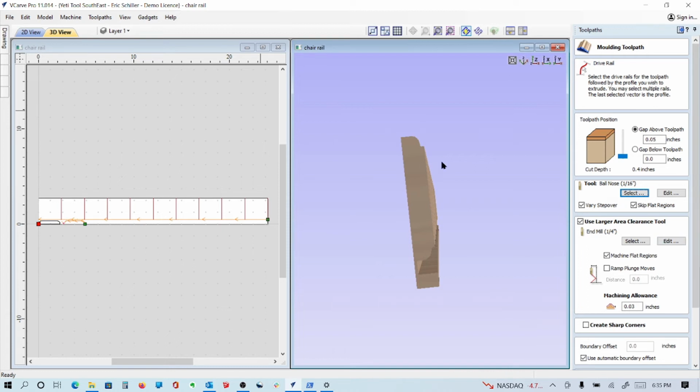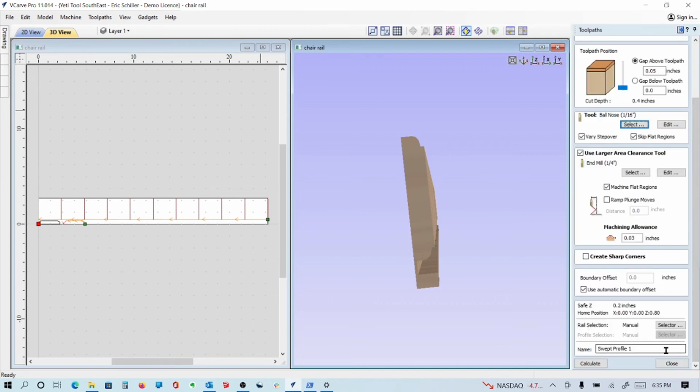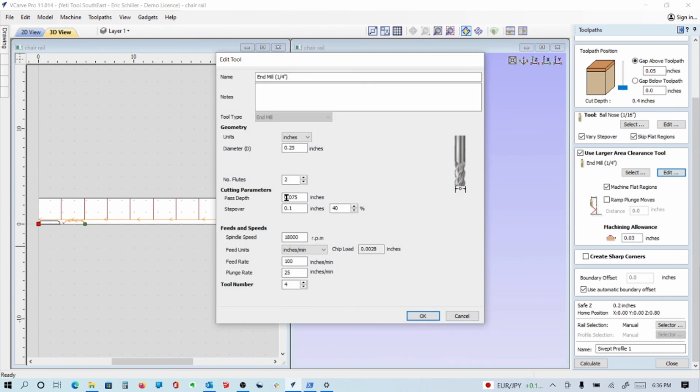And this is a flat one, so obviously if we used a bigger tool first, a 1/2 inch or 3/4 inch cutter, surface that, and then come back in with a 1/4 inch cutter to hog this out, and then the final cutter, the 1/16 inch tapered ball nose I'm looking at, to come in and clean that. But I'm just going to leave it like this for this time. So we're doing a 1/16 inch, but we're using a 1/4 inch tool to hog out the bulk of it. And we can control the step overs and things like that here. I'm going to make that 80%.